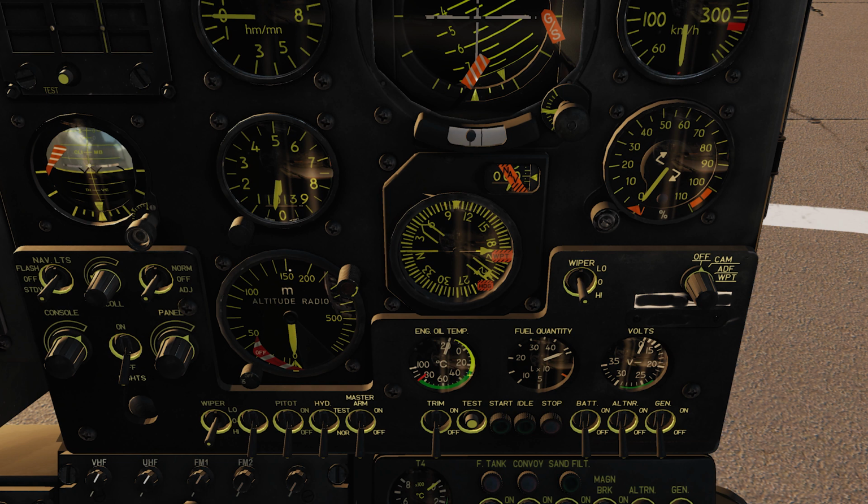So in the next row, we have our engine oil temperature here. As you can see, it is colorized because pilots are easy guys. We have a yellow arc for the low temperatures, a green arc for the normal operating temperatures, and a red never exceed line. As long as this needle is in the green, you are totally fine. That's what the instrument is telling you.